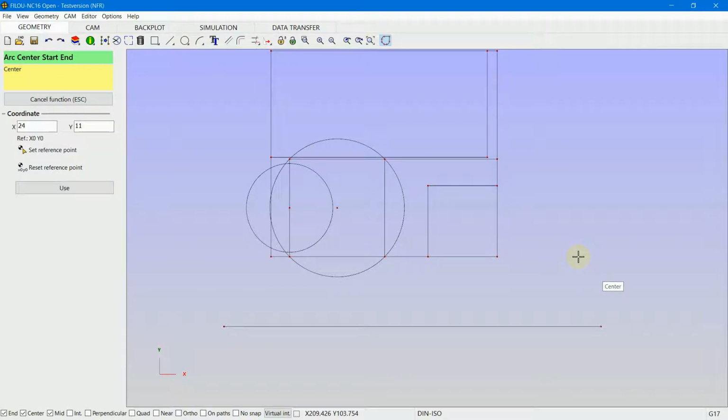I do it here. The first point is clicked somewhere, and I can always enter values, but now I do it by mouse free. I press shift to make it straight, and now I click the first point, and I can drag the arc, and with ortho I can set exactly 90 degrees opening angle. Arc 3 points is very good when I have to trace geometry, when I have to make a corner somewhere like this.